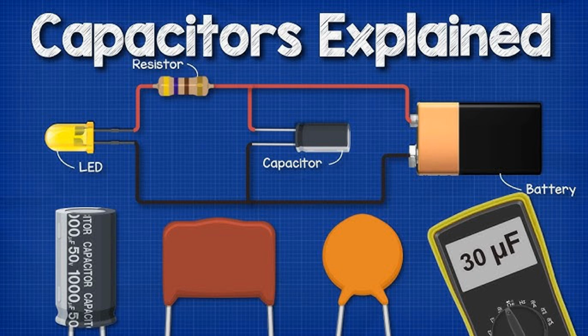Decoupling capacitors. Description: capacitors are placed near the power pins of integrated circuits, ICs, to stabilize the voltage supply and filter out high-frequency noise. Application: in digital circuits, decoupling capacitors prevent voltage spikes and noise from affecting the performance of microcontrollers and other ICs.